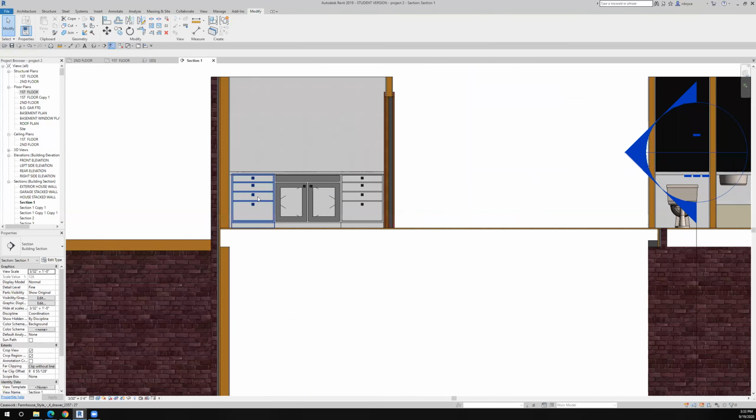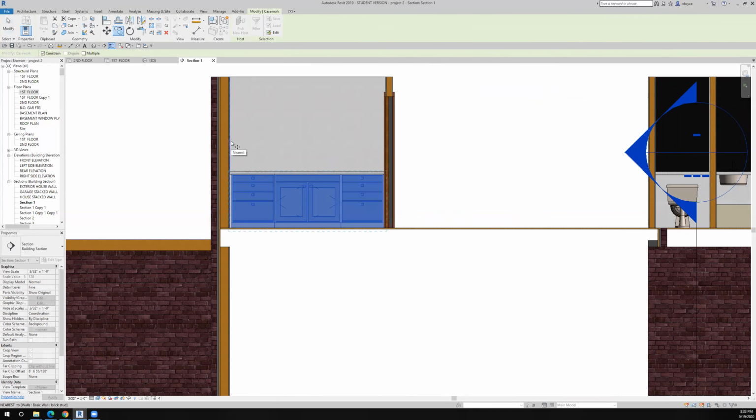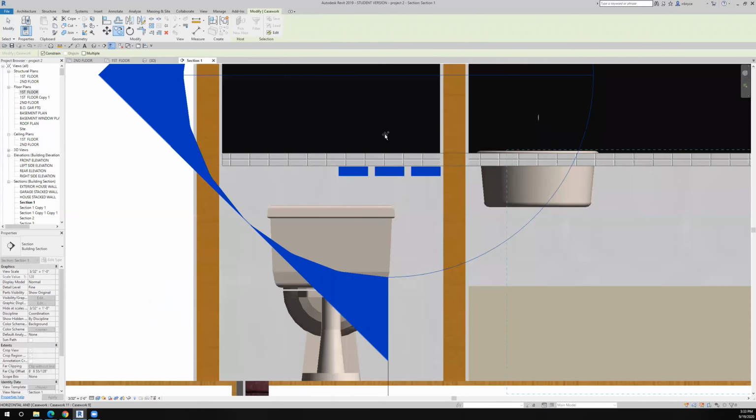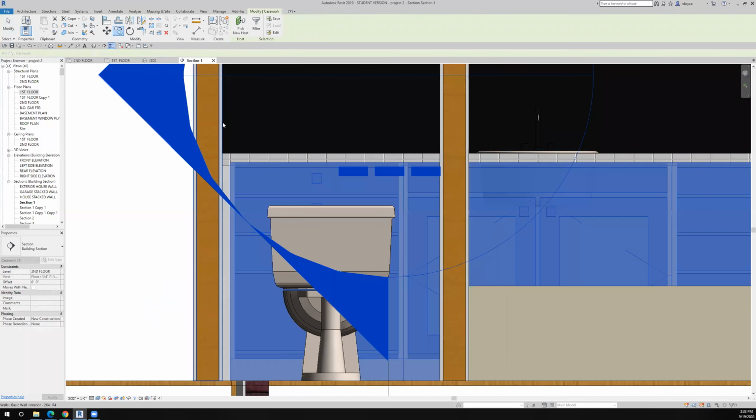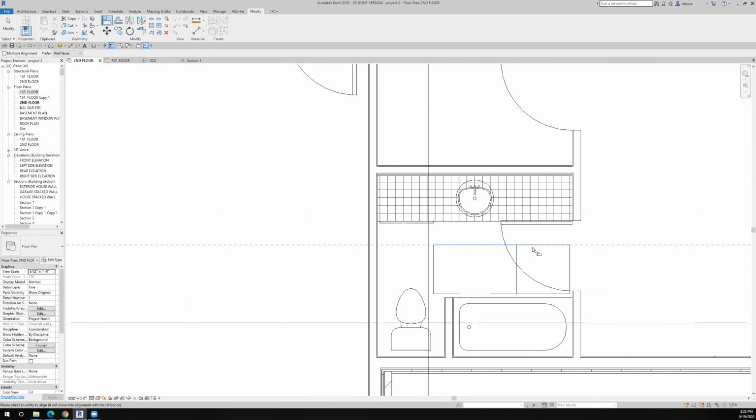And I want to copy 3 more things. 1, 2, 3. And I will copy them from the edge of this wall over to the edge of this wall. Go back to the floor plan, and I'll see that it's out a little bit too far. So I'll use my align tool and pick that, and align this guy, and this guy. Whoops, I didn't have multiple lines selected. So I want to pick this, and I'm going to say multiple alignment. So it's going to let me align more than one thing to the line that I wanted everything to be aligned to. All right, looks good.